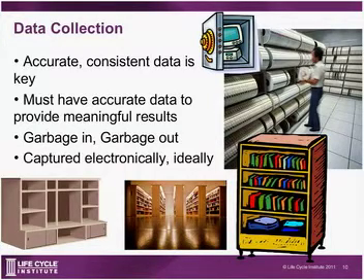One more comment on data, and that garbage in is garbage out: ideally we would capture our data electronically. If we have foremen or operators turning in reliability data or uptime data to their foreman at the end of the shift, how do we know that data is reliable? How do we know it's done the same way every time across multiple shifts with multiple personnel? If we have a program set up that forces us to document the data capture electronically, whether it be downtime numbers or production rate numbers or quality numbers, then not only does that data have a higher potential to be reliable, it is also there for us historically.